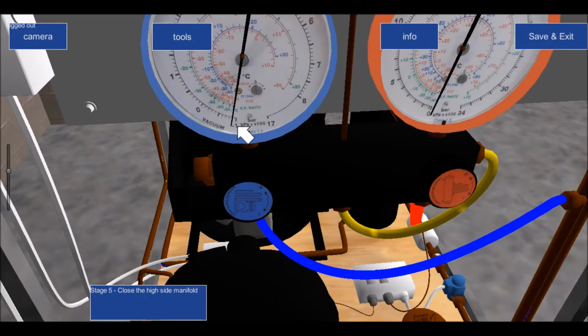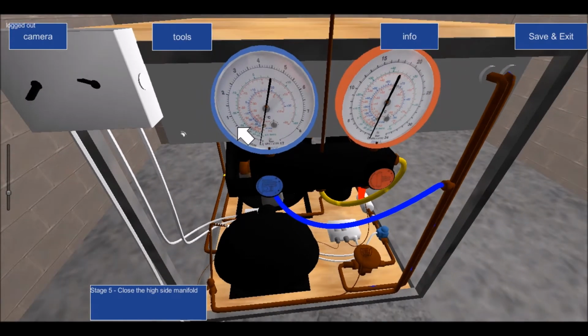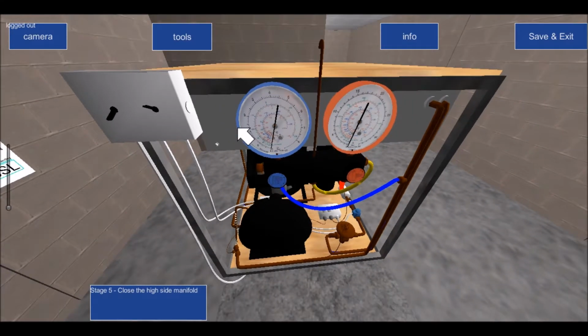See that some cold rooms don't have the solenoid valve. However, they'll leave the high pressure and the low pressure, and the compressor works through the thermostat. Yes. So that, as I said at the beginning, was the on-off cycle, and I was saying there are 2 types. There's the on-off cycle, which is what you've just described. And there's this type, which is the pump down cycle.